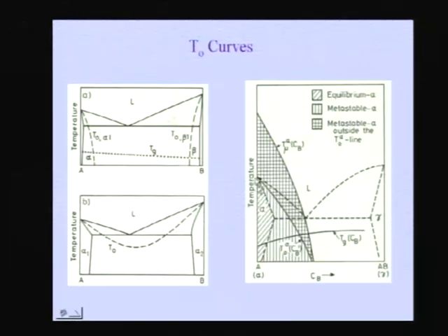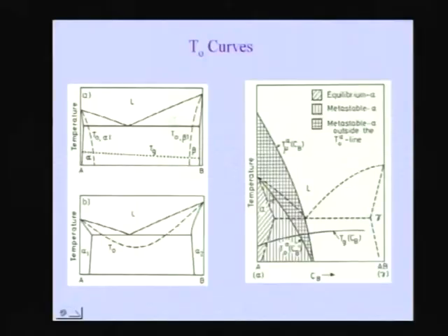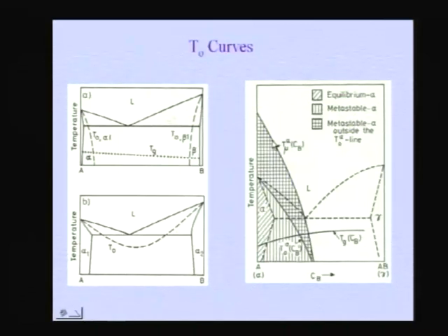If you keep on increasing the temperature, the first melting point that you will come across is the thermodynamic melting point. The second melting point that you would come across, if at all you can suppress melting at that thermodynamic melting point and keep on increasing the crystal to higher and higher temperature, is what is called TSI, which always lies between the T naught and T mu. That is the temperature where the entropy catastrophe comes into the picture, and the crystal will catastrophically become a liquid. If you somehow suppress that, which is impossible, then you will come across the shear modulus going to 0, and that is the other catastrophe. These are all theoretical concepts, and practically reaching those temperatures is very difficult, but physicists work on all these possibilities, and in principle these are all possible.